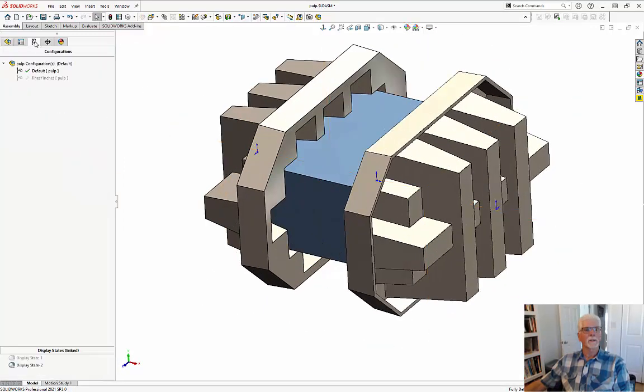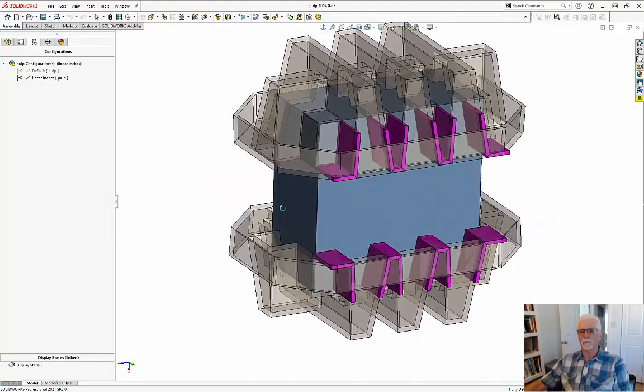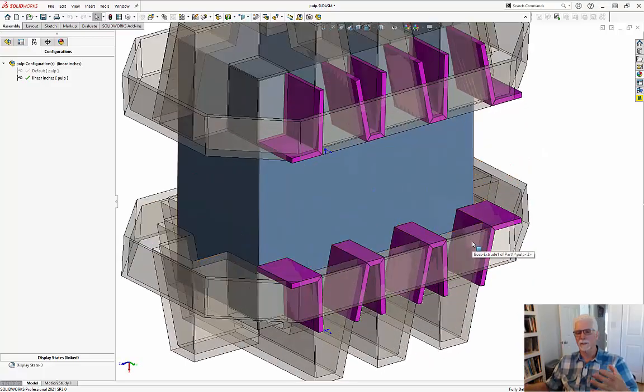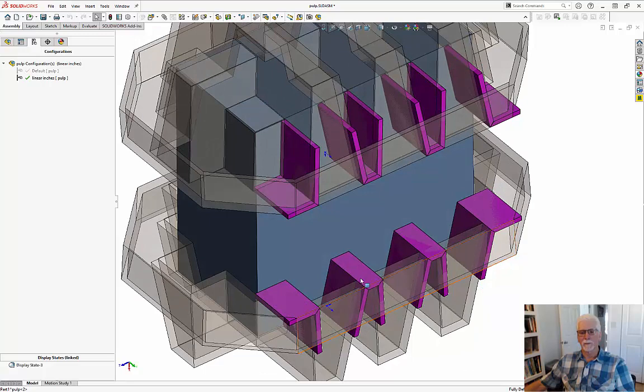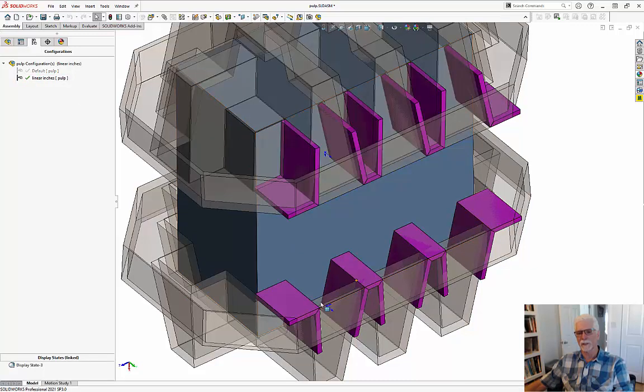But if we drop it against that one side, it's going to look more like this. So the surfaces, or I should say walls, because it has a wall thickness, so that wall thickness is shown in pink. If it falls, let's say, straight down like that, these pink walls are the walls that are going to take all the loading. Let me go back and forth real quick. So there's what it was when it wasn't transparent, and then these are the walls that are going to take all the loading.